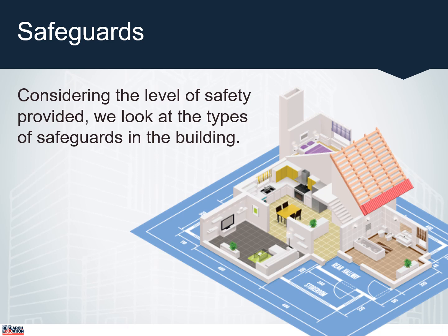Which direction do the exit doors swing? Doors swinging opposite the direction of exit travel create significant additional risk, because people exiting the building can easily become crushed against a door that swings inward. What's the maximum travel distance within the building? The shorter the better from a safety perspective. Is there a fire alarm system providing notification to the occupants? Is there a fire detection system providing early detection of a fire?